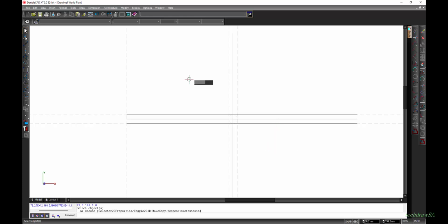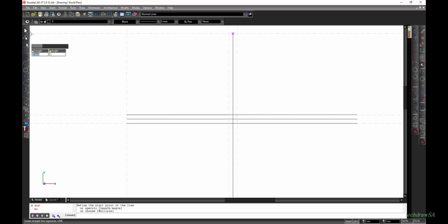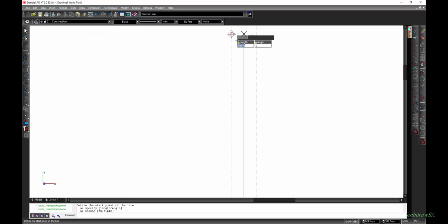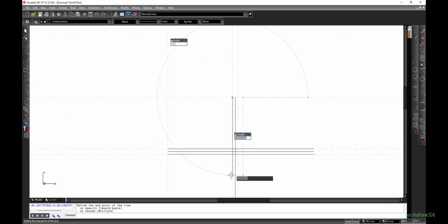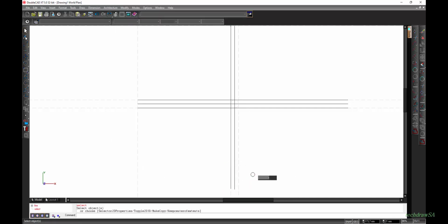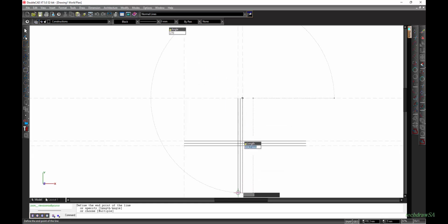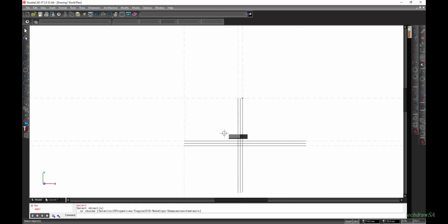Now I want to do the vertical margin line. So for that, I'm just going to give myself a starting point. I'm going to put a construction line there so that I have a reference point from where I can draw my margin line. So I'm going to select the line tool and make sure that it is on the constructions layer. And then from there, I'm going to snap on that intersection, hold shift, zoom out and draw it down. And I'm going to make sure that it snaps to that length, escape. And then I'm going to do the same. You can also use the scroll bar here if you don't want to zoom in and out the whole time. I'm going to hold in shift and drag it to the desired length, press escape to get out of it.